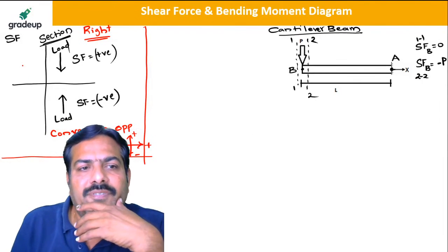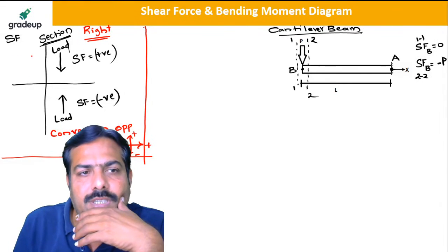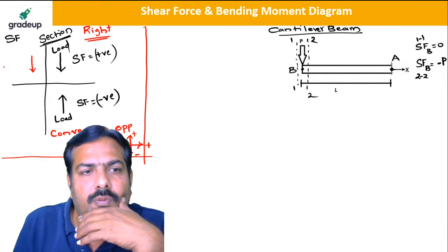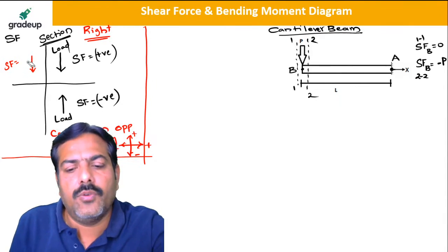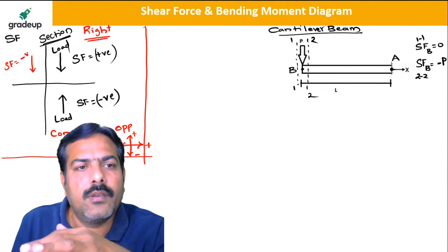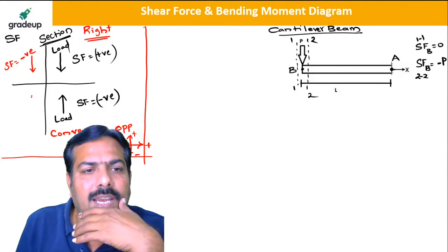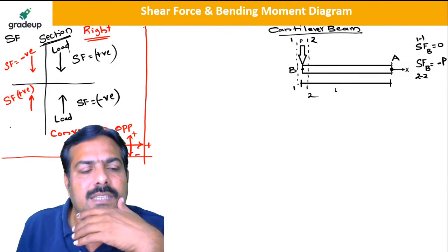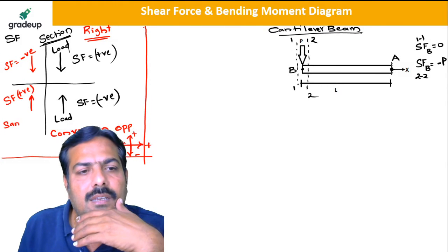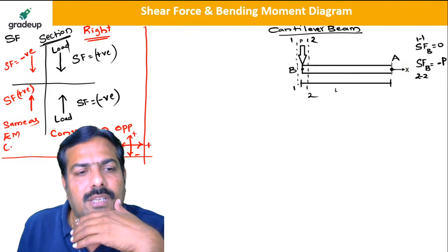So on the left side, you see, my dear friend, if the force is acting down, the shear force is negative, and when the force is acting up, the shear force is positive. Means you are taking it as it is, the same as your engineering mechanics conventions.